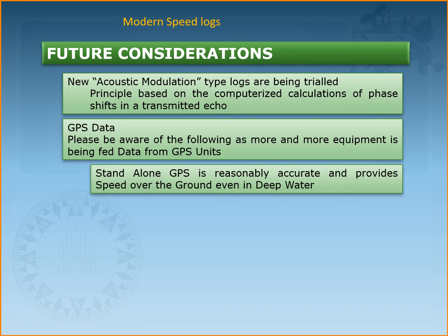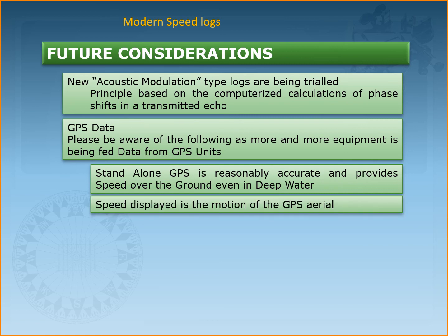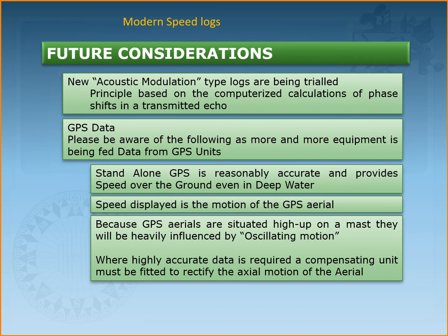The speed is estimated from the fixed distance between sensor elements divided by the estimated time delay from acoustic correlation, where two signals are compared by shifting one relative to the other in time and choosing the time shift where the best match is found. A somewhat similar method is used by the GPS receiver to get the time difference between the code received from a satellite and its replica in the receiver system memory. These electronic acoustic logs are capable of giving both speed through water and speed over ground, as they do not rely on the passage of water past a sensor but rather on the reception of the echo.